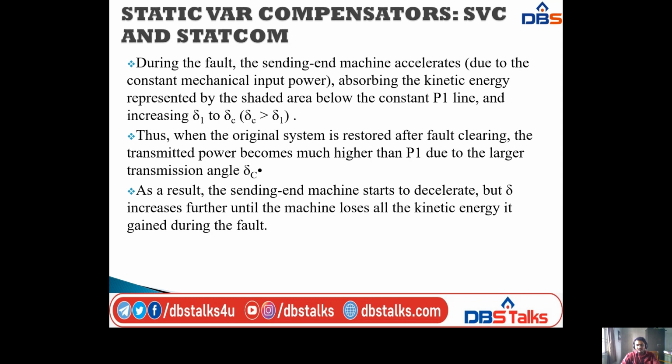Next, when the original system is restored, that means after fault clearing, there is nothing changed in the curve. So when the original system is restored after fault clearing, the transmitted power becomes much higher than P1, due to the larger transmission angle delta C.